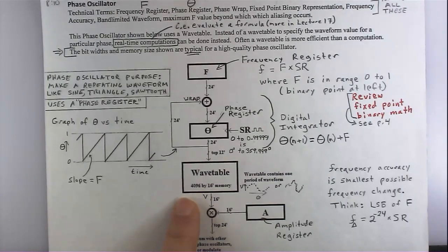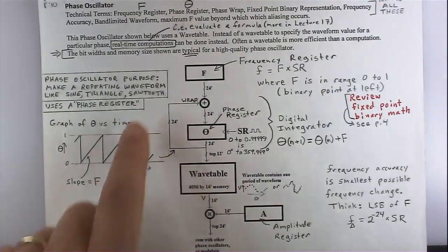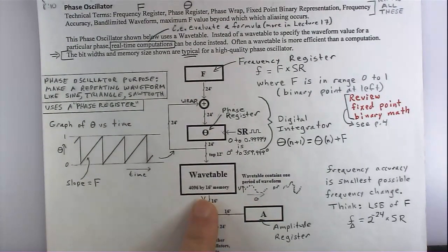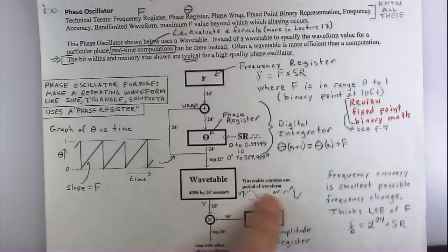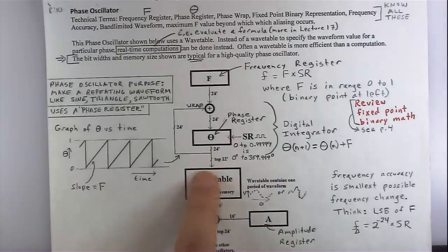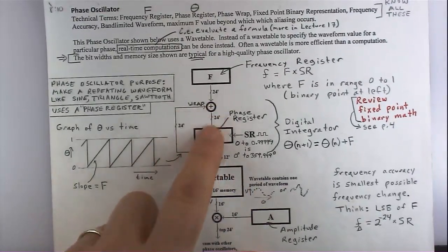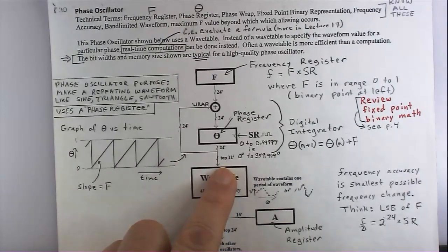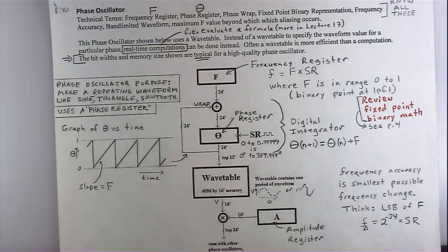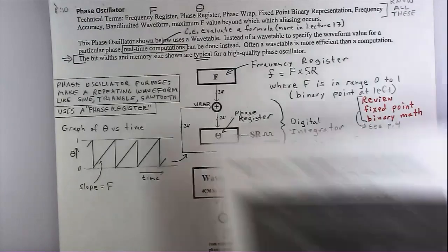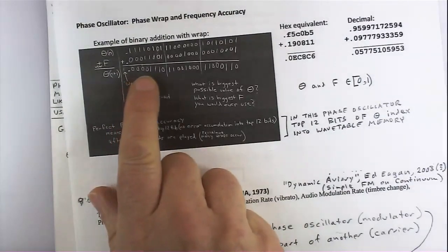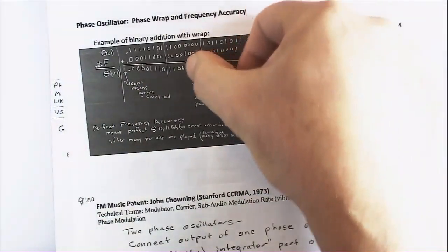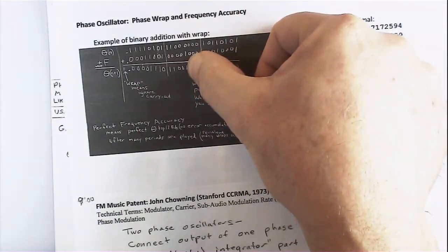What is actually happening here? Well, you're stepping through this thing, and if you look at neighboring values in the sine table, say you're doing a 1,000 hertz sine wave, and you filled it with a sine table, or you can put other waveforms in there. What's happening here? You're incrementing here. The top 12 bits aren't just incrementing by 1. They're incrementing by some larger numbers. Like if you look at the example I had on page N here, 1, 2, 3, 4, 5. The top 12 bits goes to there. Right, so you got a lot of activity.